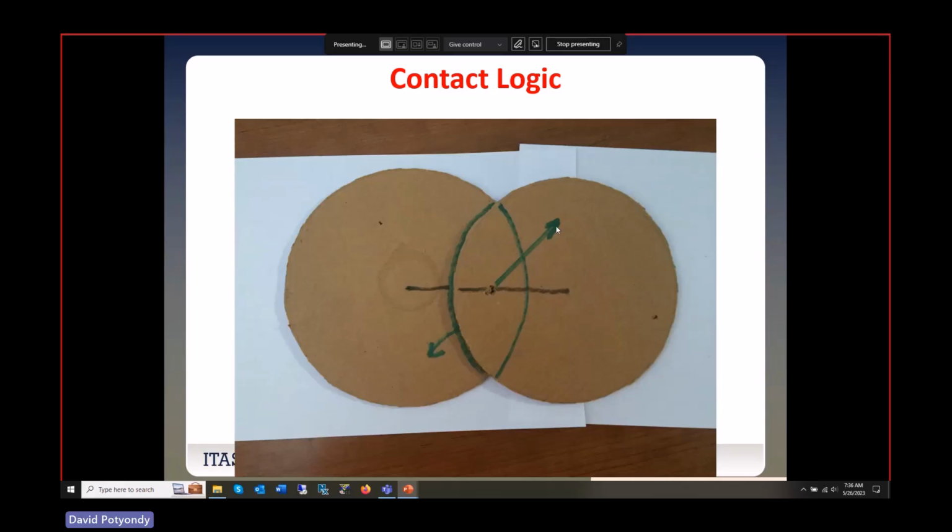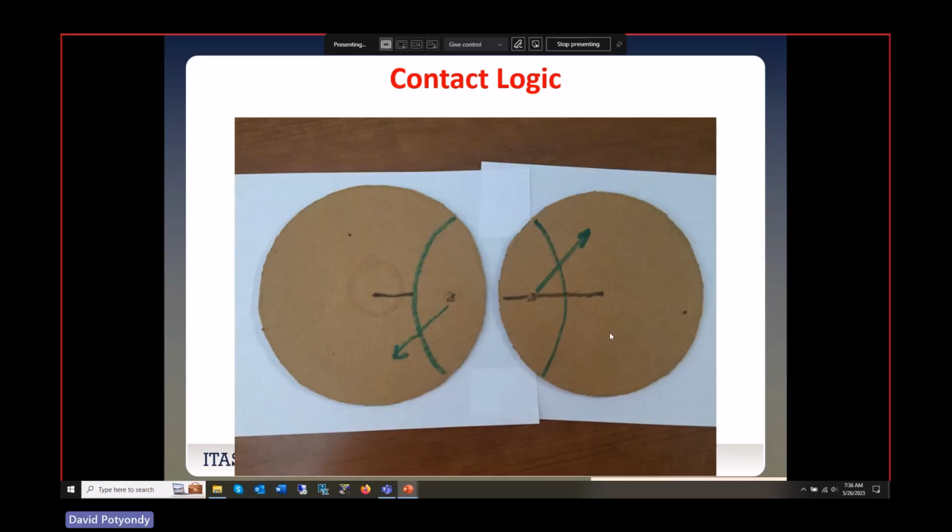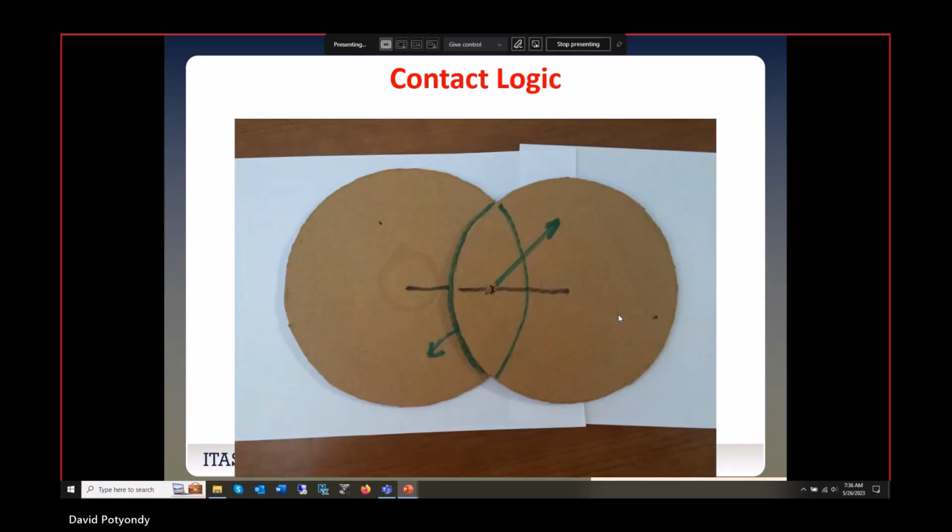This is the equal and opposite force that's acting at that location on the two discs, which is shown here. When I sum up the total resultant force for this guy about its centroid, notice this is where the force acts. It does not act on the boundary, okay? Because we do this, these systems are still going to make physical sense even when the overlap becomes relatively large compared to the radius, okay? So that's the idea. Every contact has a position in space. In 3D, it's going to be the same thing. Now there's going to be an overlap volume that we're going to be worrying about, okay?